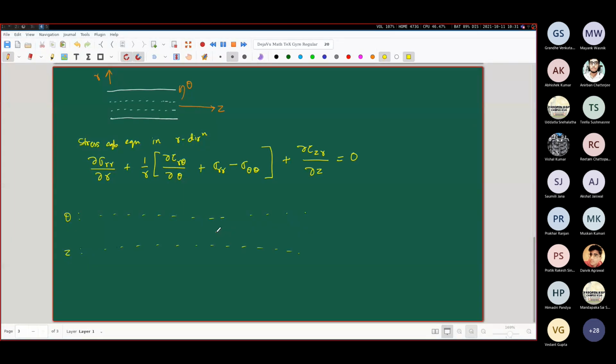But whatever they are, you tell me one thing. First of all, how many equations are here? There are 3 equations. How many unknowns are present here? Unknowns means how many stress components which you don't know anything about. So 6. Yes, there are 6 unknowns present here, the 6 stress components. So if anyone thinks that they can solve these 3 equations, they're fooling themselves because it's just not solvable. You have 3 equations and 6 unknowns. How will you solve it? No matter what mathematical tricks you pull out, you are not going to solve it.